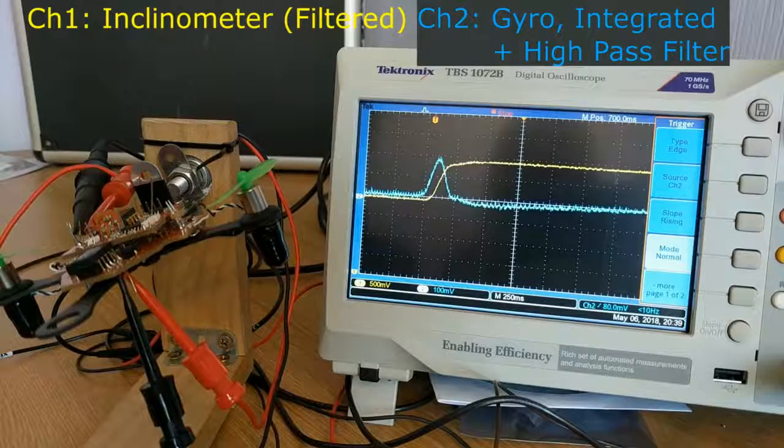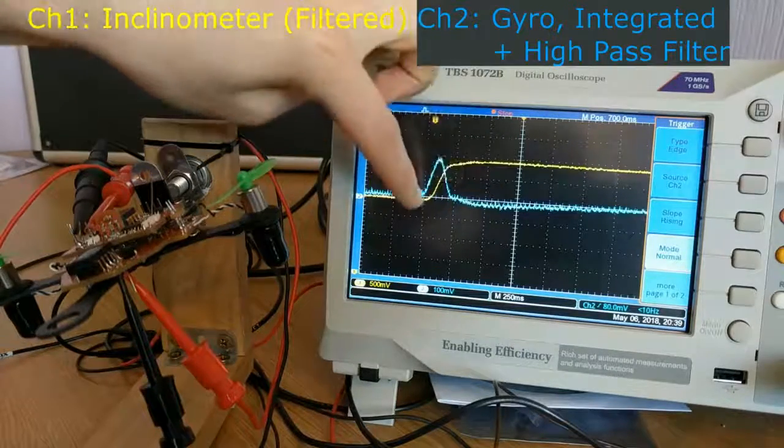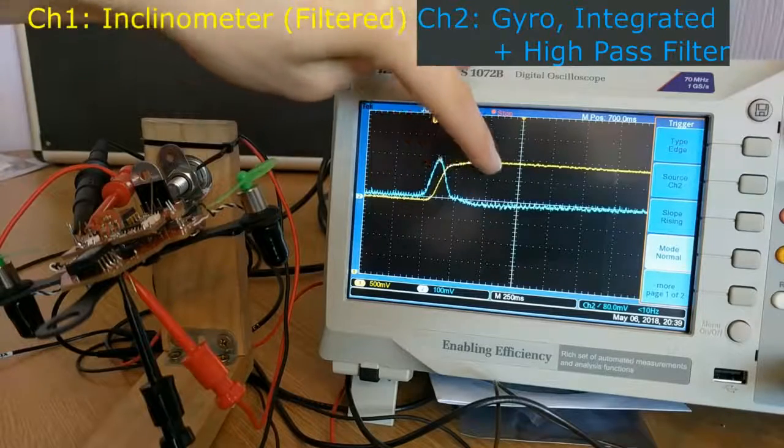This slow response can be sped up by using a gyroscope. A gyroscope measures angular rate, and I've integrated its output to give a pulse with the correct pulse height to fill the gap of the slow responding inclinometer signal. This can be seen on screen. This is the gyroscope pulse, which is filling the gap of the slow responding inclinometer.